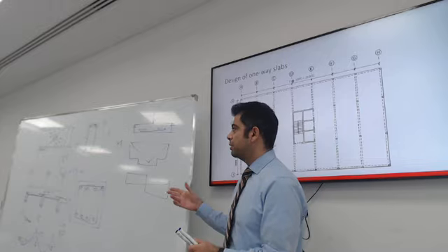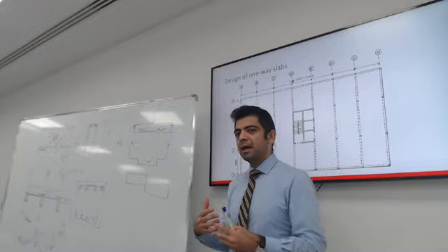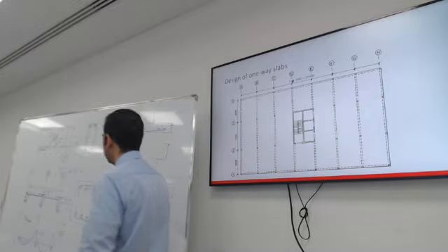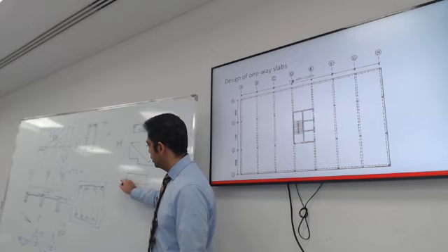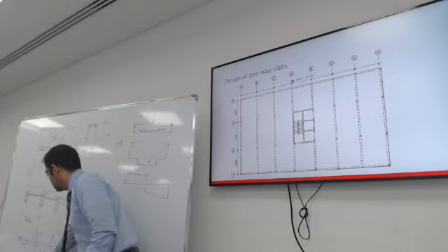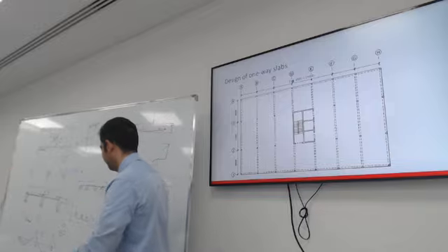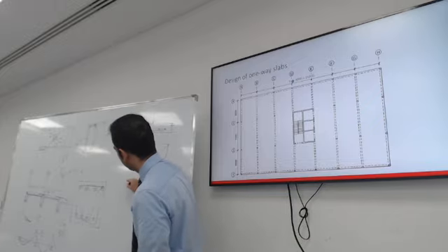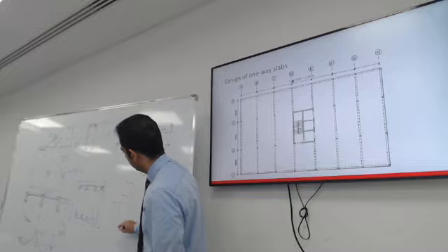This is a slab. We designed the beam last week. How do you design a slab for bending? So how do you design a beam for bending? First, calculating the compression force and the tension force, and then you calculate how much. Yes, exactly. You calculate the compression block, the neutral axis...